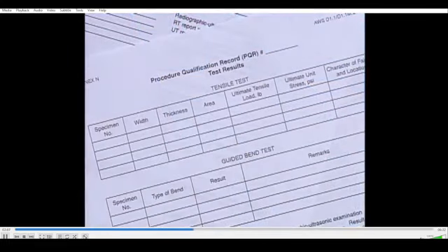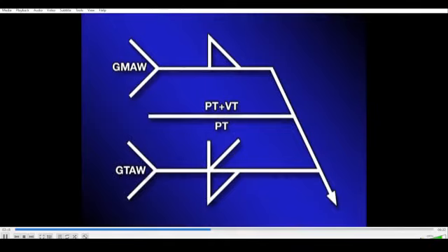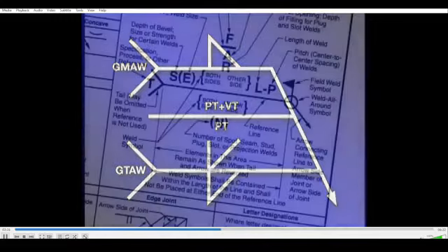Once a decision is made, it is the job of the quality assurance engineer to provide the details of inspection to the qualified inspector so that the weld is inspected according to requirements. When non-destructive testing is required, special symbols and written testing procedures are used to indicate the type and extent of inspection necessary. These need to be understood for inspection to be effective.